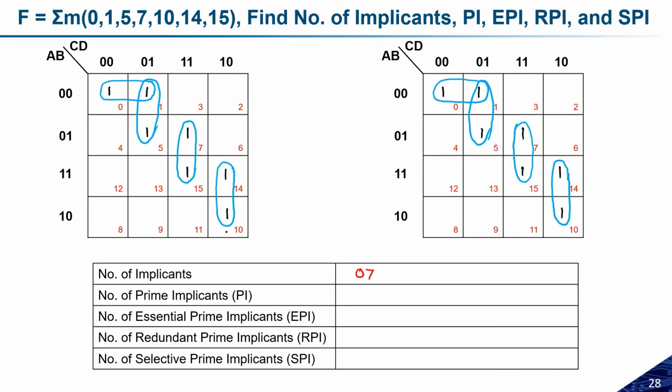See, I just told you that prime implicants means all the possible pairs that we can make in any of the K-map. So we have the possibility that I can also make the pair of this one and this one. This is also possible. So the total pairs possible are 1, 2, 3, 4, 5, and 6. The number of prime implicants is 6 here, not 4.